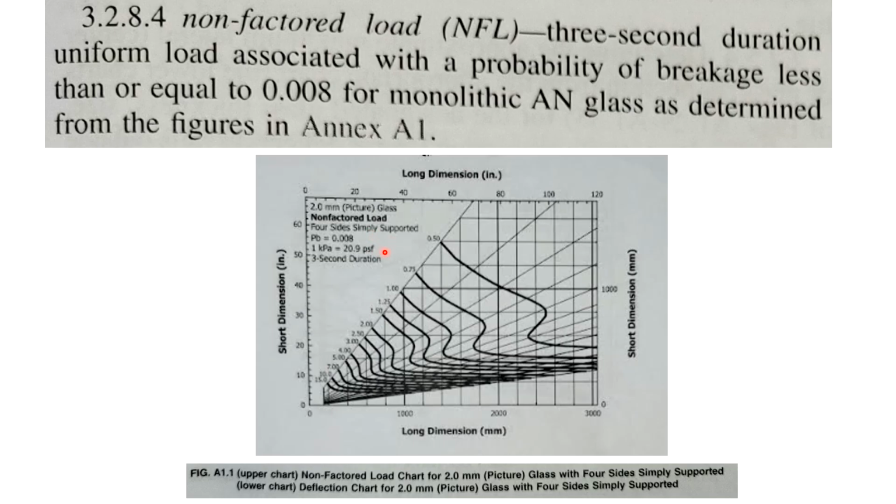Now, this is what the actual pressure is. So this 1 kilopascal is going to be equal. This is actually in kilopascals, and if you want to convert it to PSF, pounds per square foot, you're going to have to multiply times 20.9. And this is a 3 second duration. So all these are going to be 3 second durations.